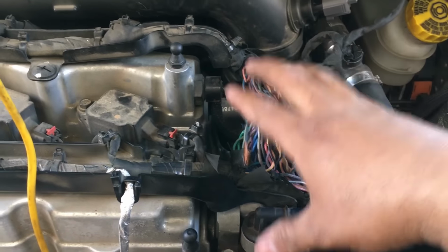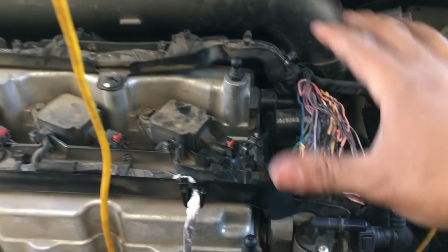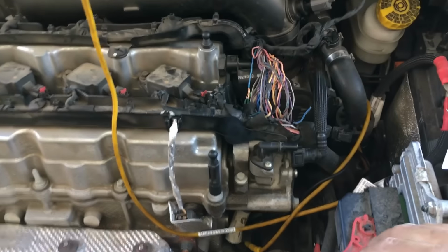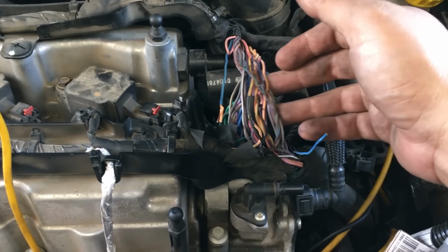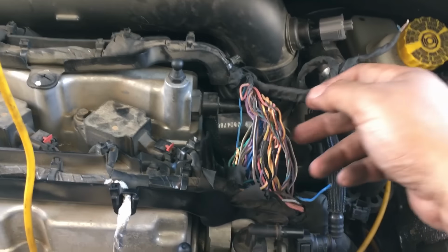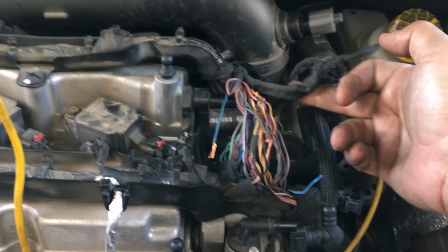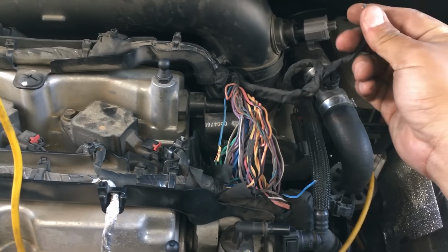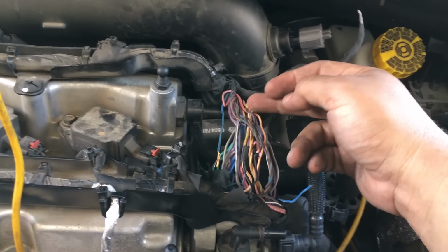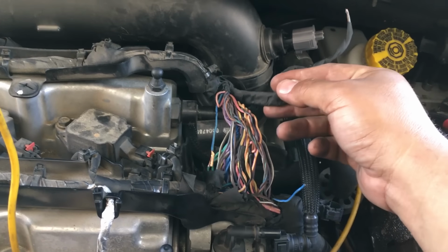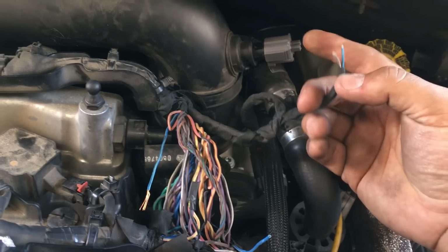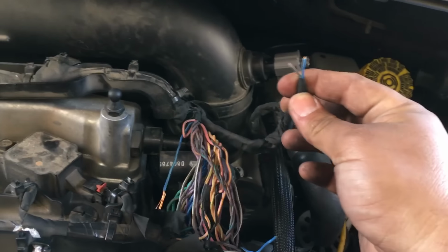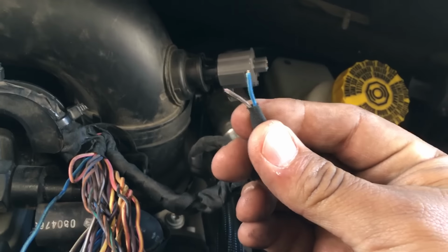I will say that this harness is located right on top of the engine, and there is a cover that goes here. So I think heat is definitely a factor as to why the integrity of the wiring is compromised here. But let me show you what happened when I went to tug on this harness right here. I didn't tug on it very hard at all. I was simply pulling the electrical tape off of here and trying to move this harness, and this actually broke clean off of the connector where the IAT sensor is, as you can see.